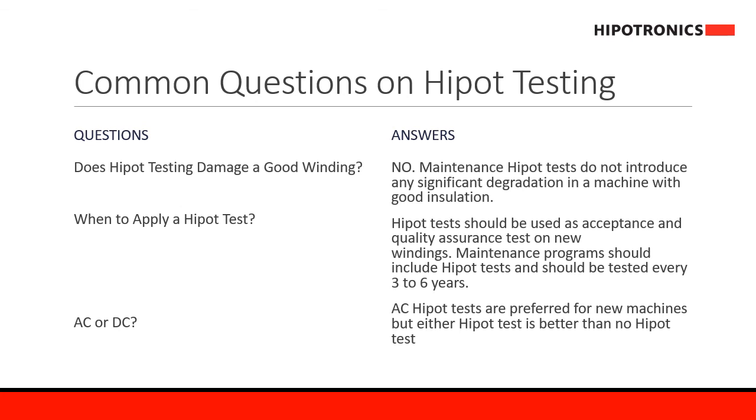The third question is what test should we consider, AC or DC Hipot? The answer is AC Hipot tests are preferred for new machines, but either Hipot test is better than no Hipot test.